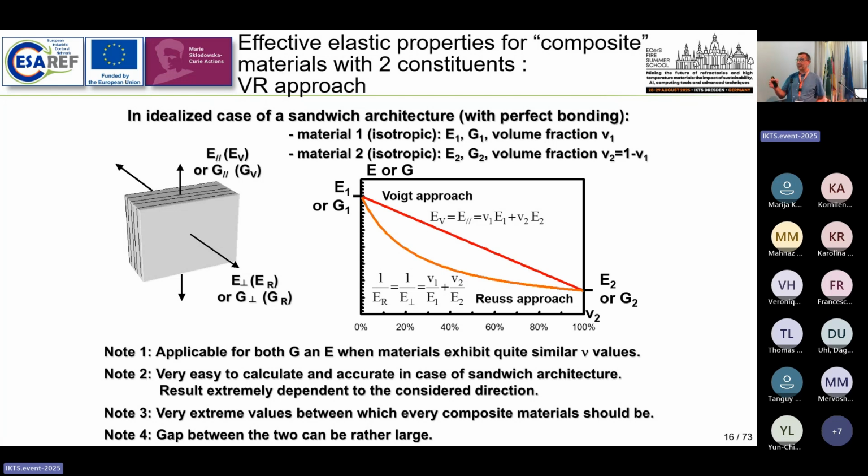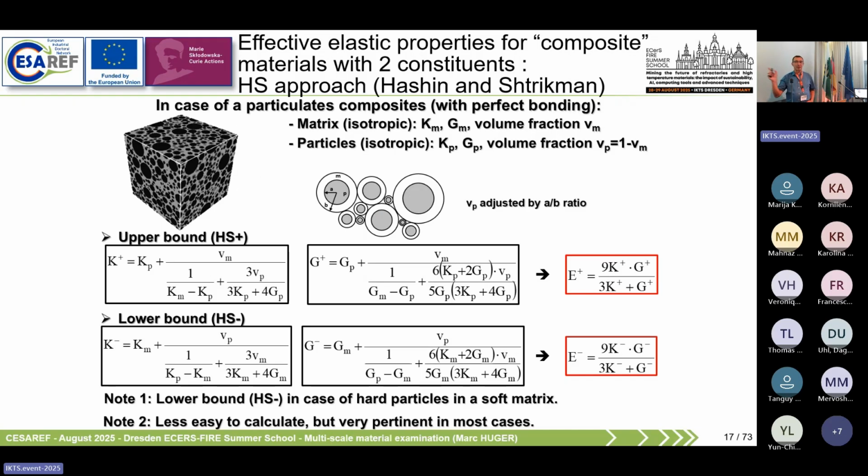Because in many cases, this is not exactly true. But nevertheless, in many papers, we want to interpret the result. Most of the people use this formulation, mixture law, which doesn't work, in fact. So take care about that. I would prefer much more complex formulation, you can find also in literature from Hashin and Shtrikman in the 70s. And in fact, this formulation works well.